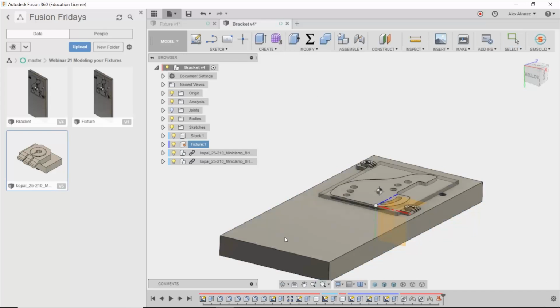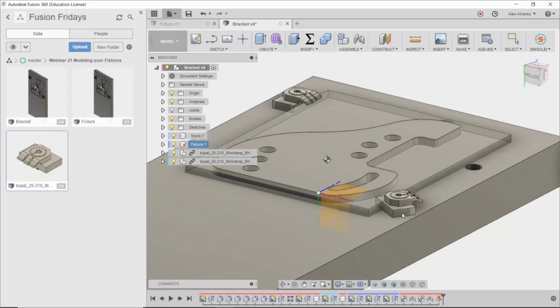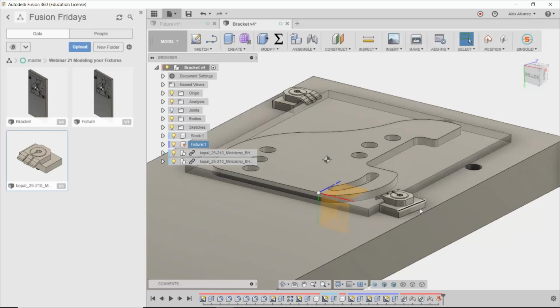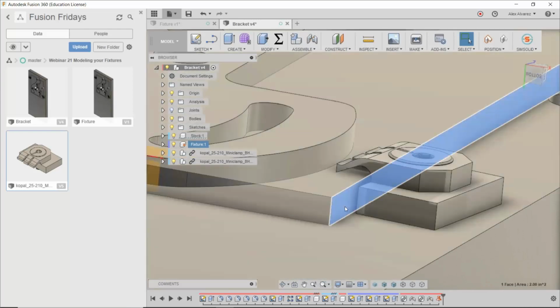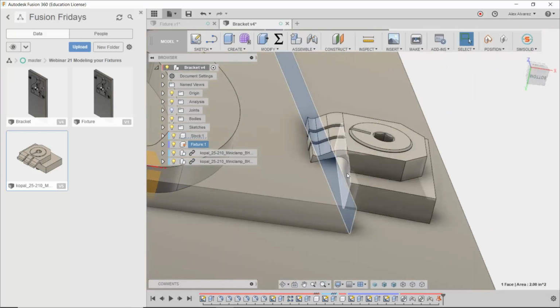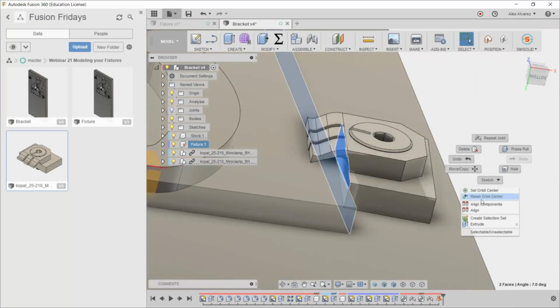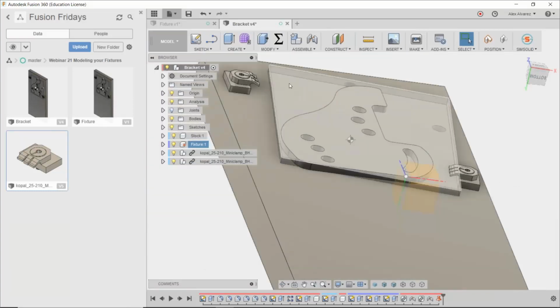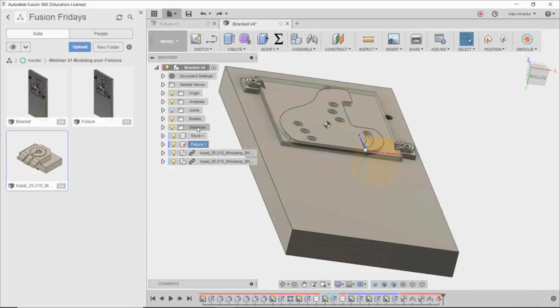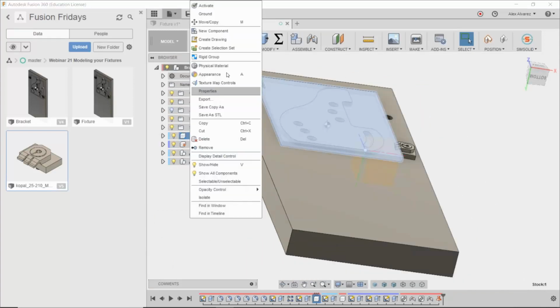So now if we try to move that, it's not going to go anywhere, right? So the only thing that should move are these clamps. And what we can do then is align these two, right? So click on that face, click on this face right here, right click, align components, right? That aligns into place. You guys want to make sure that you ground the stock as well.